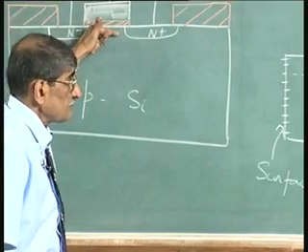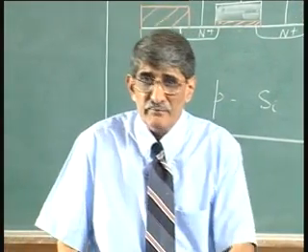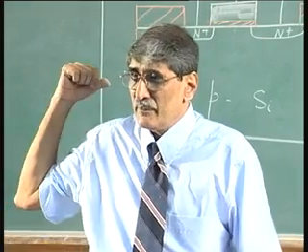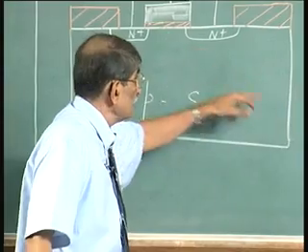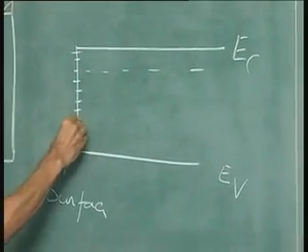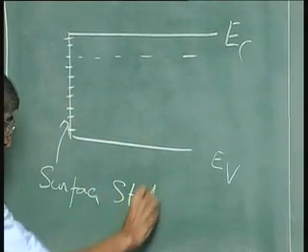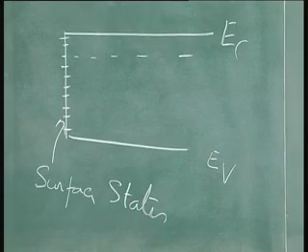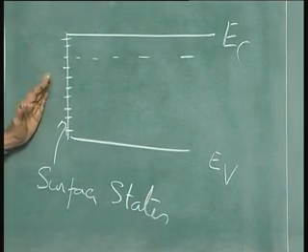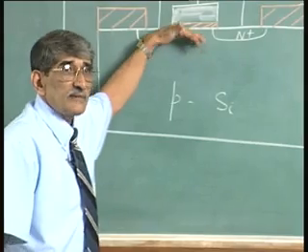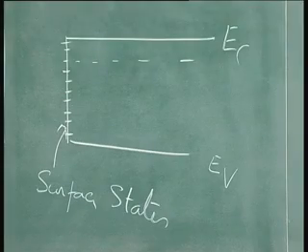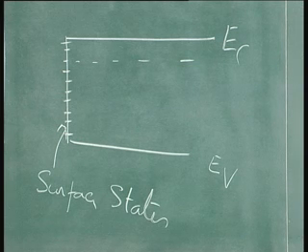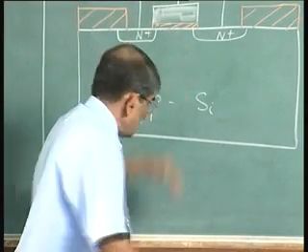That was the problem. So, if you put a deposited material, or you grow a thermal oxide, that was sorted out immediately. In fact, the transistor was invented because when they said there are surface states here, these are the surface states. If it is in the free surface, you call it surface state. If it is between oxide and silicon or between dielectric and semiconductor, you call it interface state. It is the same. Okay. So, these interface states were the problems when they tried to make these transistors.